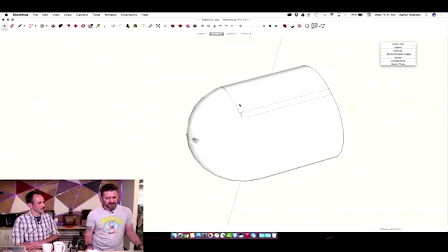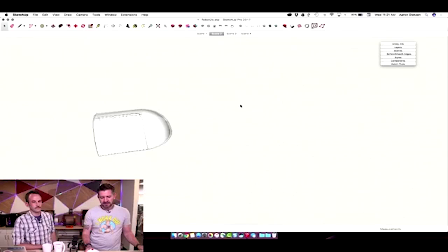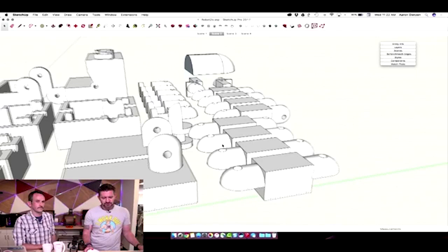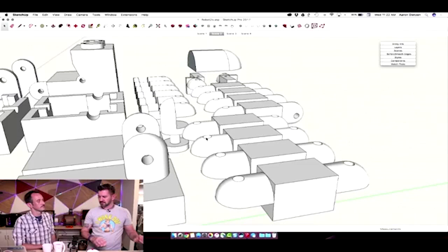And again, this is something you want to keep in mind as you're printing, because as these stack, if I print it laying down flat like this, the layers are going to stack and get smaller and smaller and smaller. I'm going to have a nice tapered volume coming up. It just prints a little bit different than, say, a rectangle, where it's real easy to visualize how that's going to print and stack. So it's something you want to be considerate of. Like I said, that's what I found out here: I want to make sure that rounded shape is on the top, because that's the way the layers are going to stack neatly.